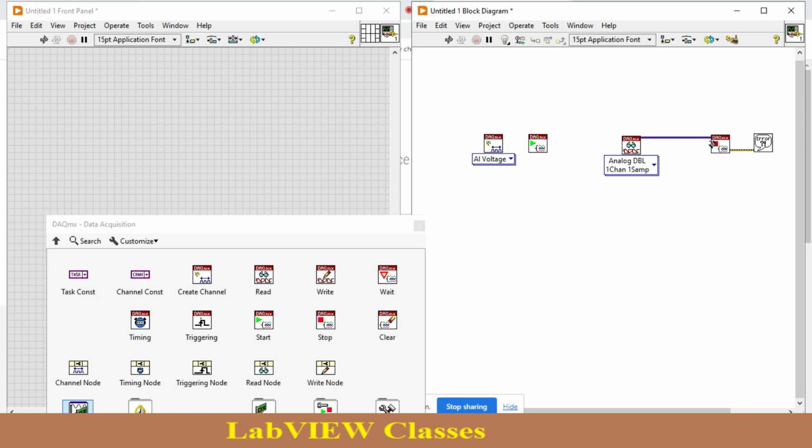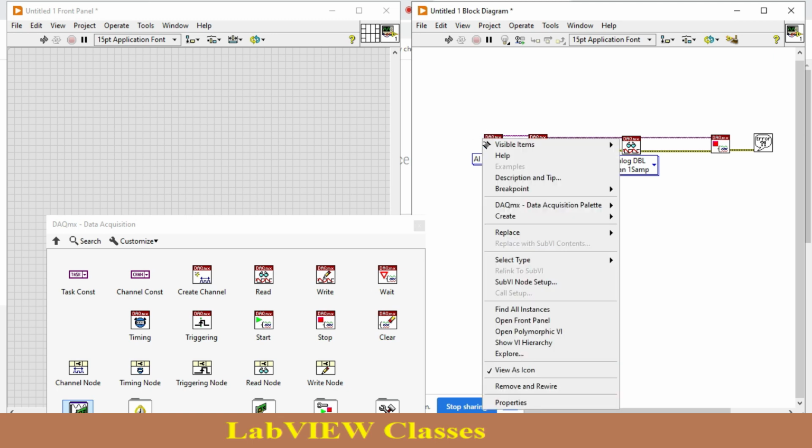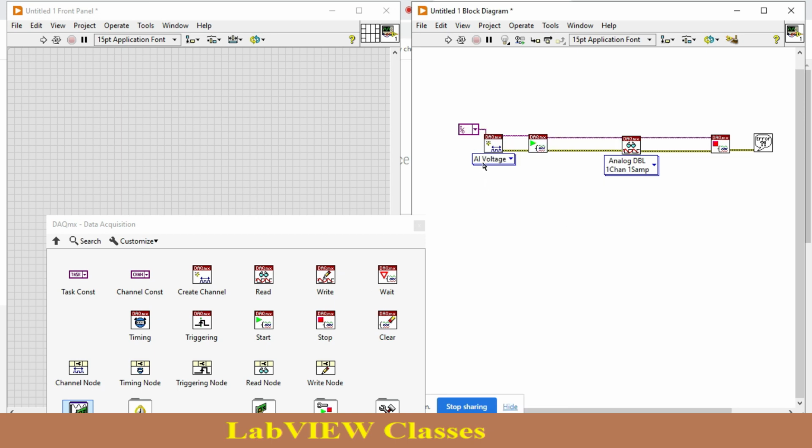It is up to you. Right now I am not using the clear function. Just connect error in to error out, and over here you need to set the physical channel. Create a constant for it, and in this I set AI 0, let's say.